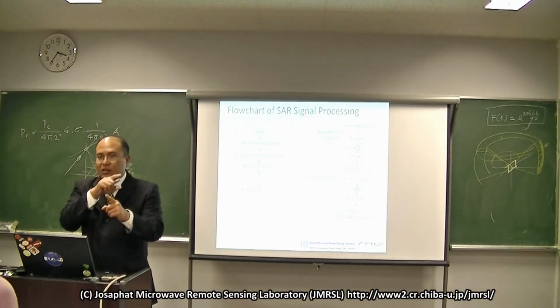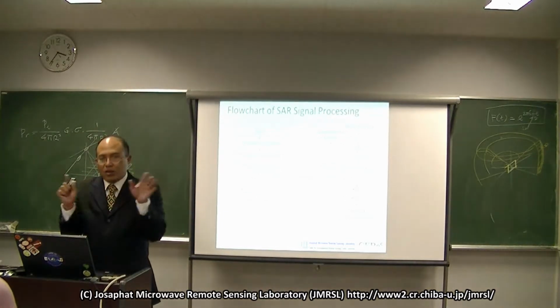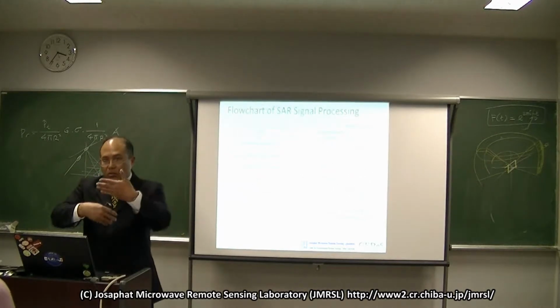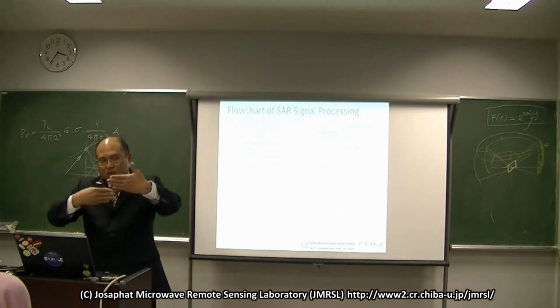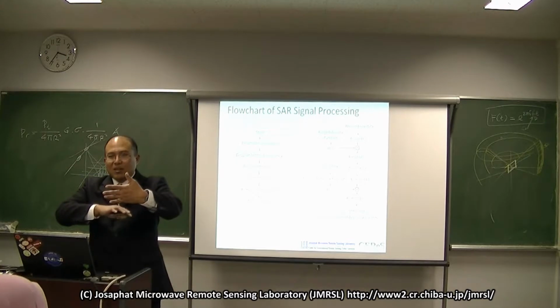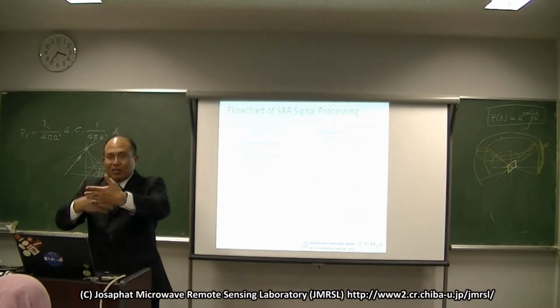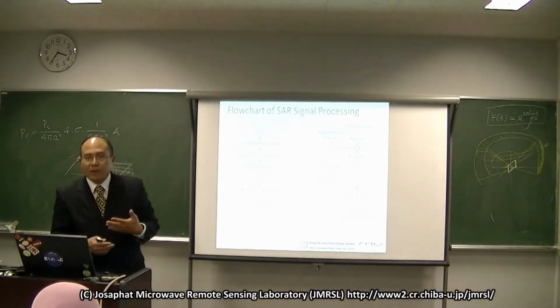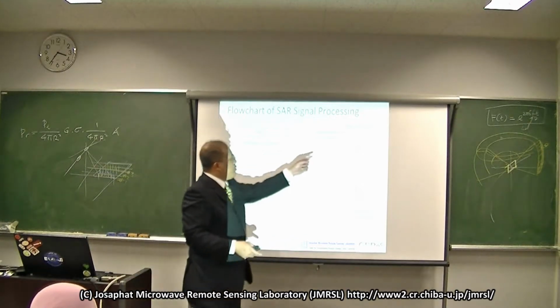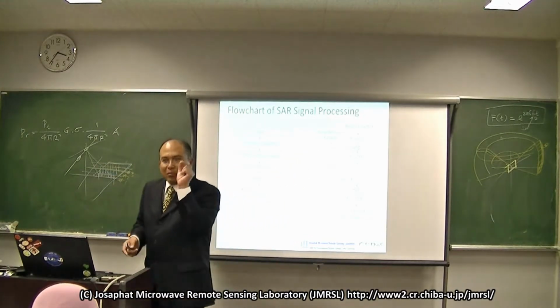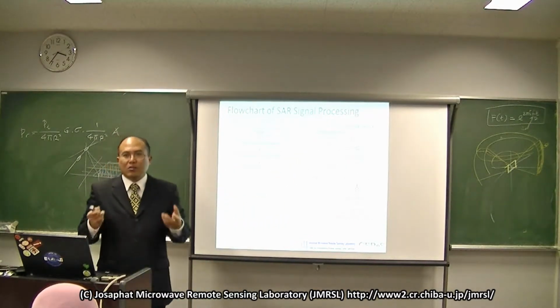Then just multiply. If not, in the time domain, cross correlation needs multiplication and then summation, which takes a lot of time. In the frequency domain, you just multiply one time. It does not consume so much time.